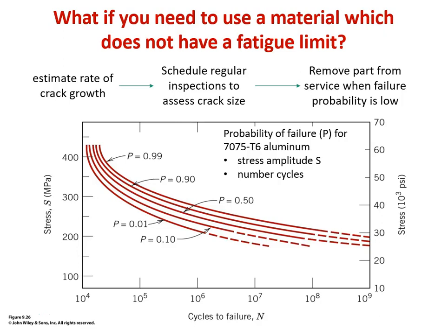We can also look at this from the standpoint of a fracture toughness type of criteria and look at how big the cracks are, because we very likely won't fail this simply due to fatigue. We will probably grow the crack to the point where we no longer meet our safety factor for our K1C overall failure.